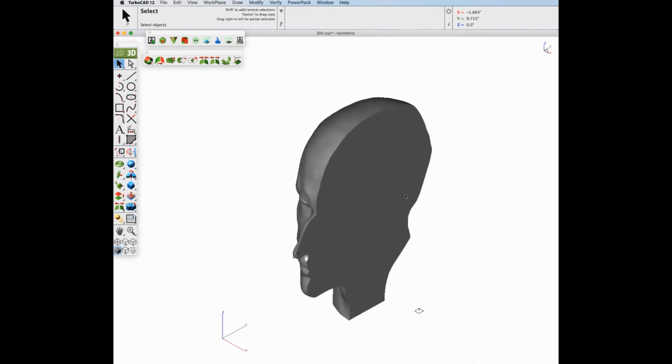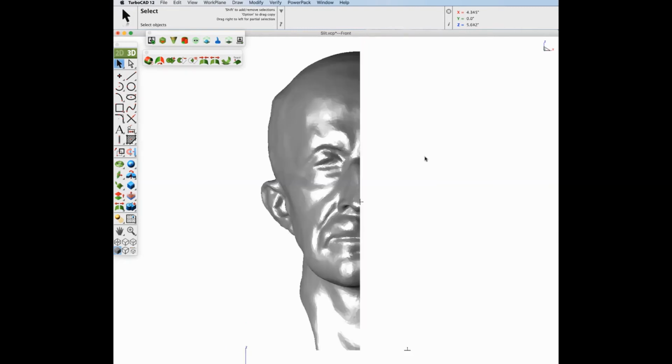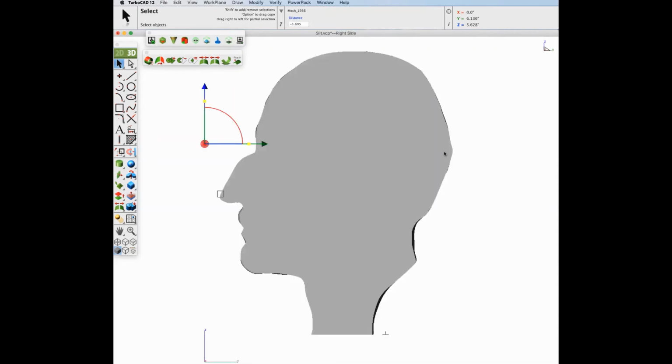And now let's go ahead and add a couple alignment holes using some mesh booleans such that we can reassemble it when we're done printing. And I will go to the cylinder tool, cylinder mesh, and we'll make this 0.01 inch radius. And let's place it relative to our part. And we'll create 3 alignment pegs.